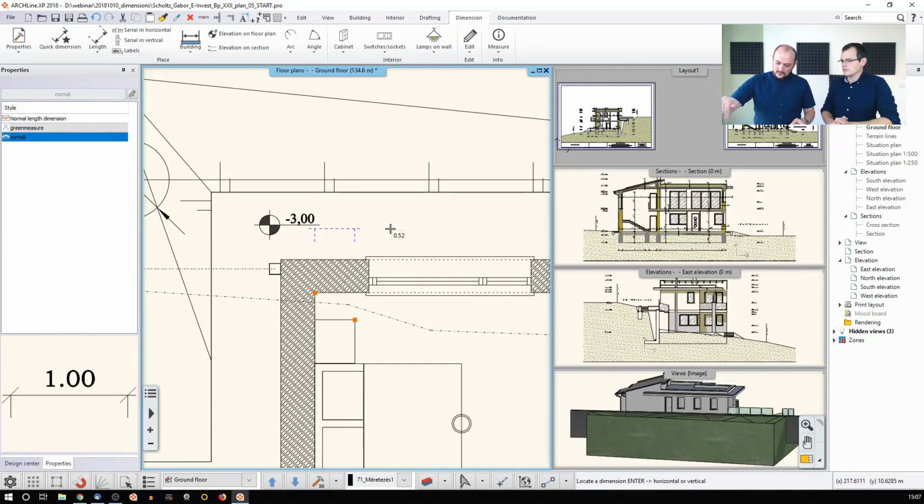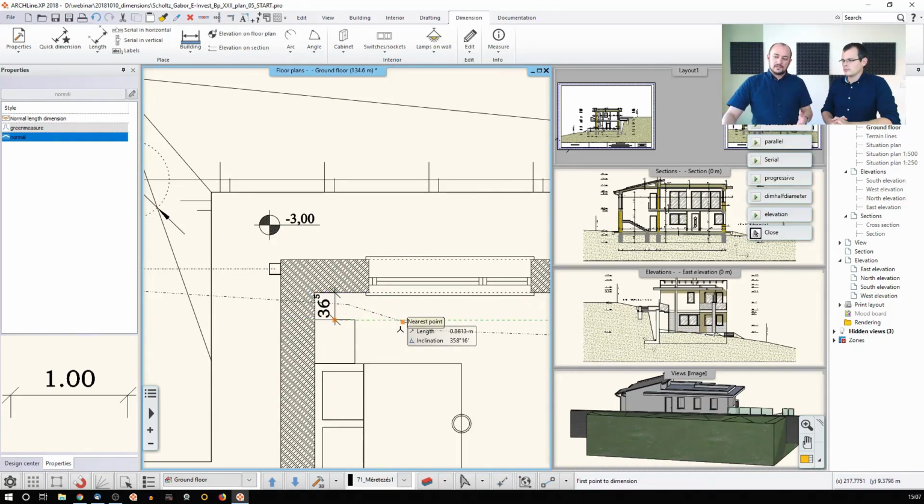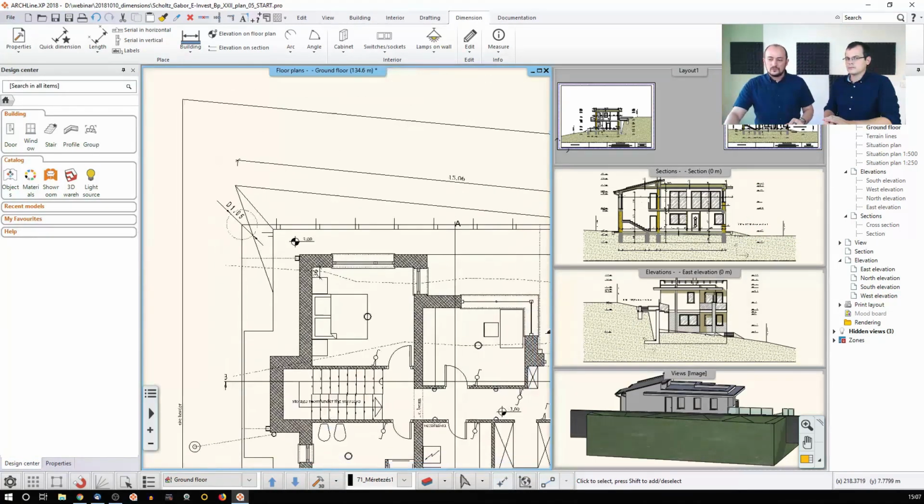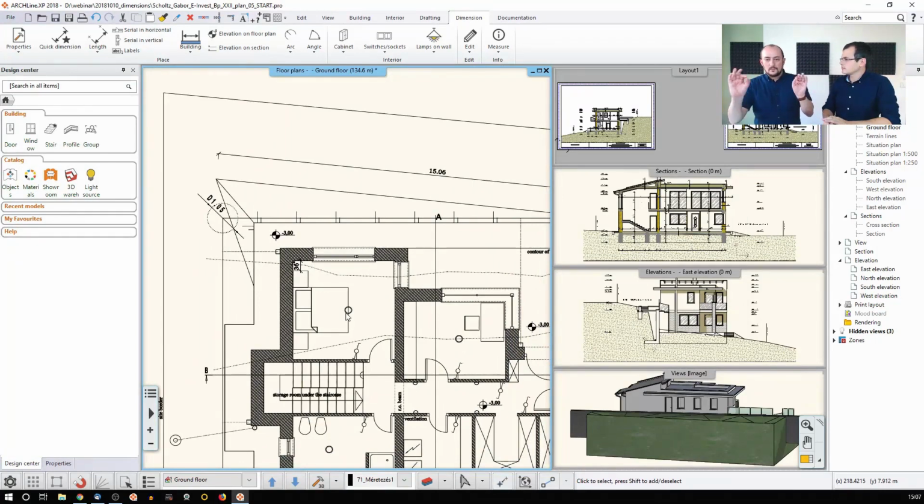If I right click again, it will switch to the vertical component, and then I just click here and the software places that measurement. Whichever component I like, I move it someplace, click, and then continue adding more and more dimensions. This is the simplest and most primitive tool to use if you would like to pick up 2 random points and measure their distances anywhere in your drawing.